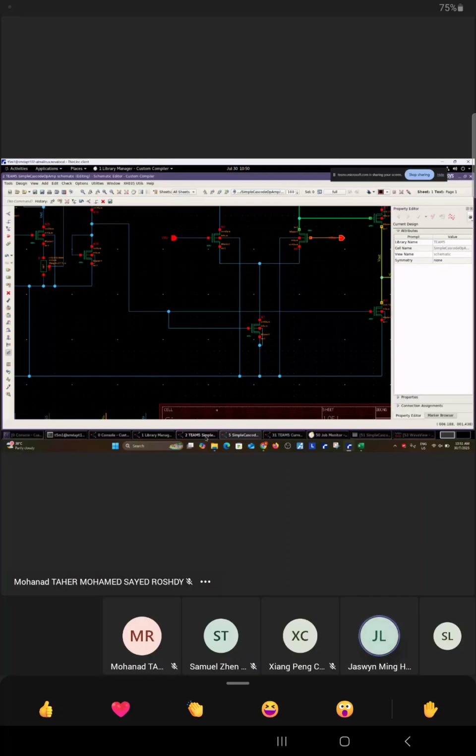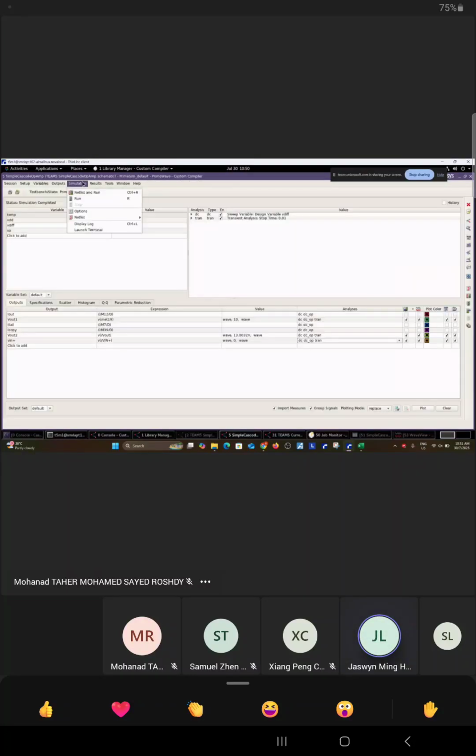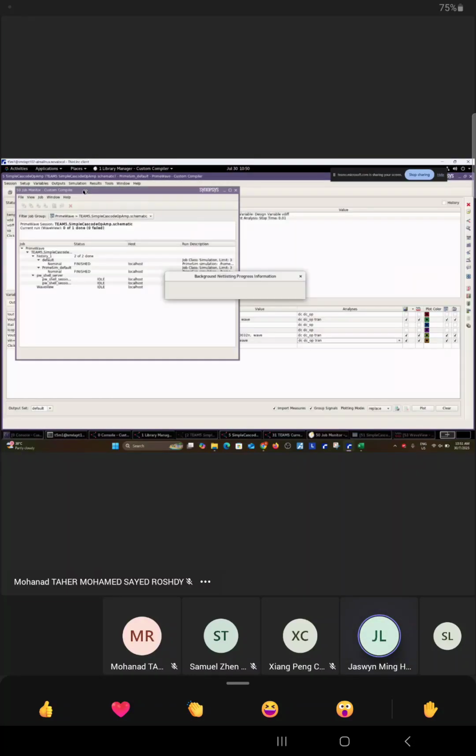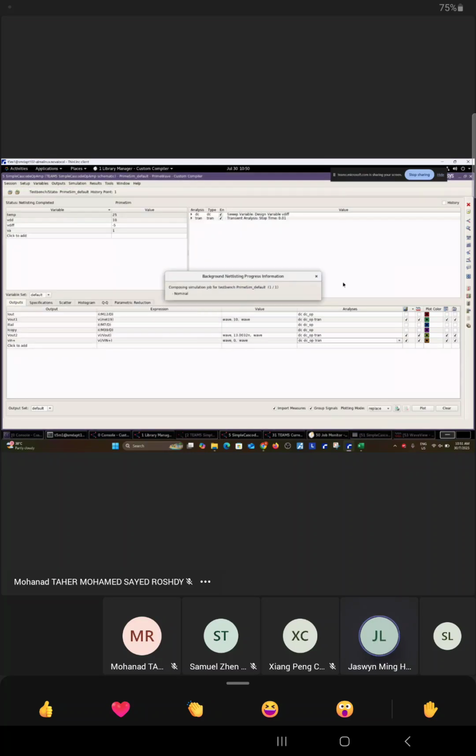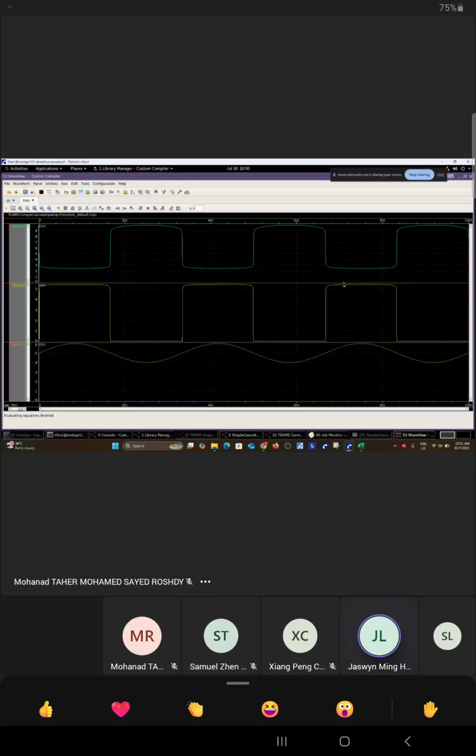If you have 2 milliamp current, I think your power is quite large for a microchip already. And I think in layout terms, Derek told me it's going to need a very, very thick, very wide metal to conduct. Yeah, still, okay, for the first stage, how can we improve further?